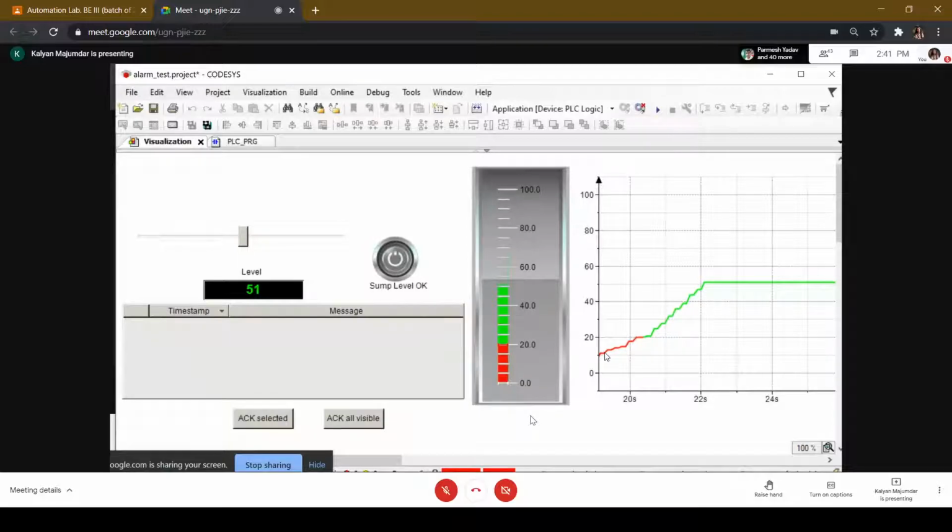Here what you're seeing is an HMI screen or visualization, as we call it in courses, that relates to the process part. You also have a visualization that is associated with your controller. Controller means the on-off controller that was developed as a part of version 1 of the assignment. There you had, or you will be making, different kinds of switches. One switch will be for auto-manual switchover. There in the manual mode, you'll have a start button, you'll have a stop button.